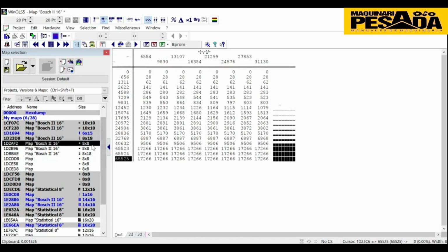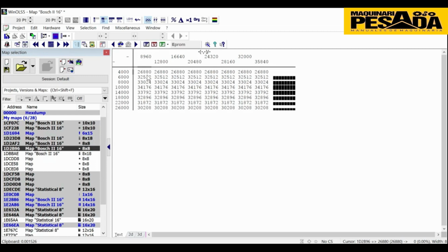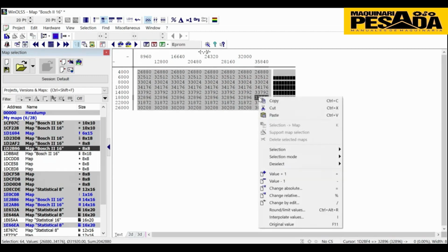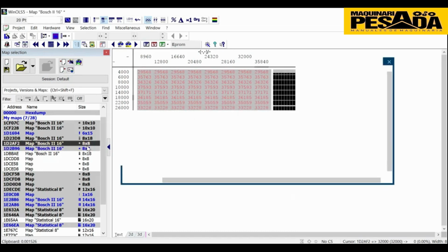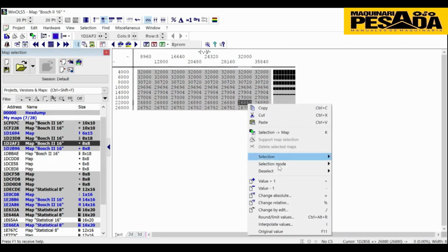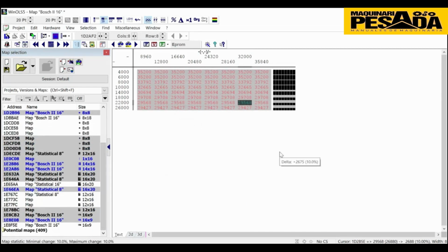throttle by operating angle. And about the turbo and limiter of turbo, you can increase the maps like that by 5%, both of them, or 6%, or even 10%, both of them. This can generate more power for the engine for the stage 1 tuning.